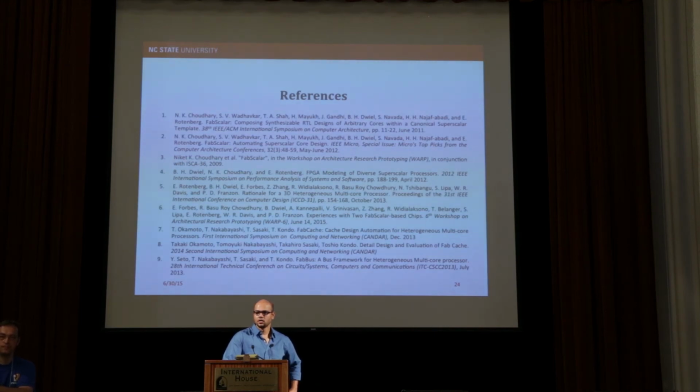Okay, and then with respect to the technology timing, clock speeds, etc., what's your experience so far? How fast have you been able to synthesize these things? Do you anticipate any issues there? So a dual issue out-of-order core, I was able to synthesize with 45 nanometer commercial technology at around 1.8 gigahertz. And a 4-issue synthesizes at slightly lower than that, if I remember correctly, 1.6 gigahertz. Do you have hardware that runs that fast? No, we don't. We haven't taped out with the 45 nanometer.